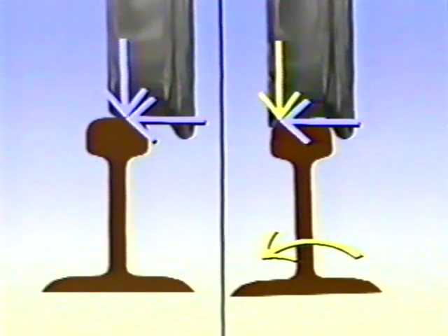As you can see, wheels with false flanges have a much greater tendency to roll the rails than properly tapered wheels. This is the reason that some railroads are experimenting with beveling the field corner of rails and curves to avoid false flange wheels contacting the rails on the field side.